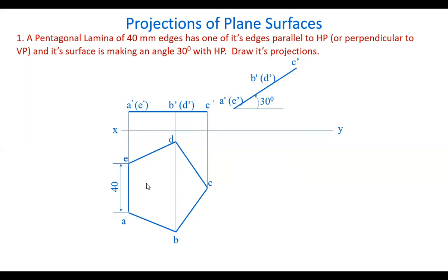Coming to these points in the front view, we have marked D and E within brackets, because when you look at it in the front view in this direction, A, B, C are nearer to the observer and D and E are away from the observer. So D and E are kept in brackets. Now, from all these points, draw projectors here like this.